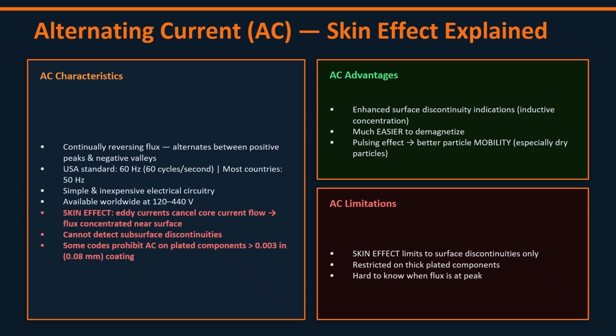However, the inspector must pay attention to coating limitations and procedure requirements. A coating can separate the particles from the leakage field and reduce sensitivity. Some specifications place explicit limits on inspection through plating or coating.